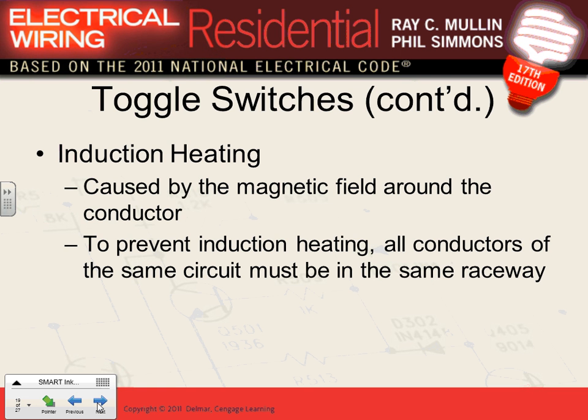The reason for that was that they were carrying one conductor in a metallic conduit. If you carry one conductor in metallic conduit, guys, you create an inductive heat. Depending on how much current you put in this conductor, if it's 500 kcm, you're pulling 380 amps, you can create a lot of inductive heat to the point where the conduits or the connectors will be glowing because they're hot. So inductive heat is a big deal.